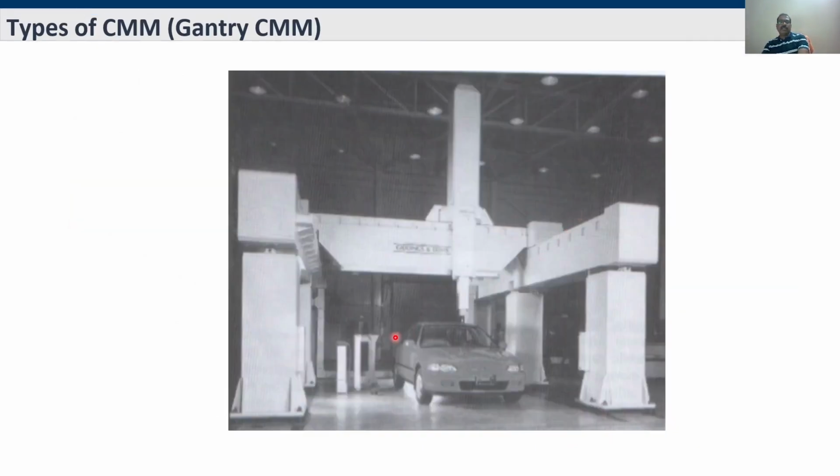You can see this one. The vertical columns, the y-axis, the z depth. So you can increase here. You can see 1, 2, 3, 1, 2, 3 is there, or you can have 4 or 5 or 6 also. But that metrological lab setup, free from vibration and all, is needed. A special setup is needed for this kind of CMM machine.